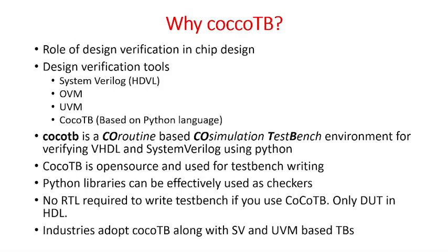As far as this particular thing is concerned, we can think about functionality checking, right? Functionality checking and then latency checking. These are two cases. Especially the assertion can capture the bugs effectively. In the case of the design verification arena, SystemVerilog has different features, because as we already know, it is an HDVL, a hardware description cum verification language.